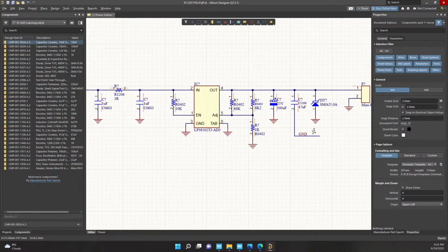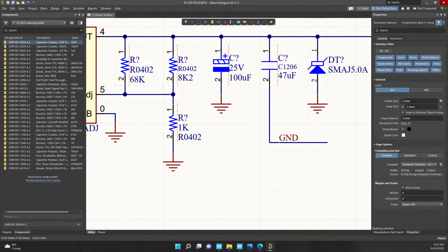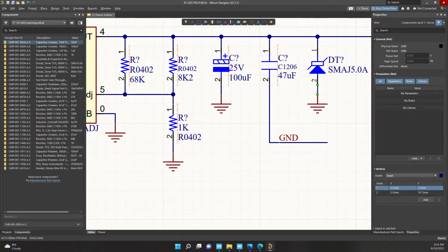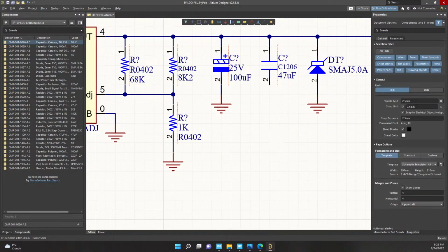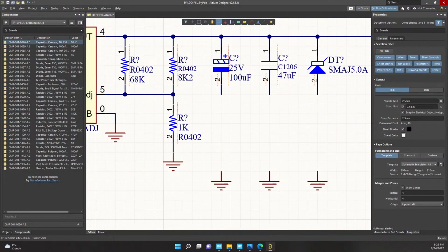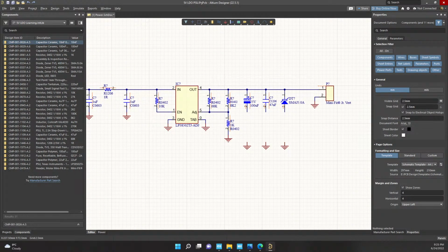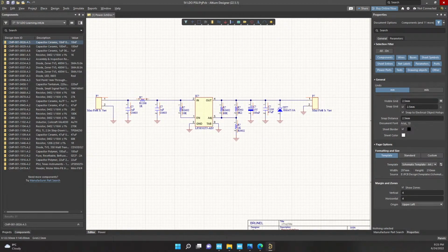This proves to us that two wires could be physically disconnected, but should they bear the same name, they are linked. Okay, that is also the reason why, instead of having, say for instance, if I didn't have these ground symbols, I would have had to do this. I put a wire like that, right? Now this becomes very unclean. Some people prefer this, some others don't. I am among those that do not, but whatever you want to do, you can do.